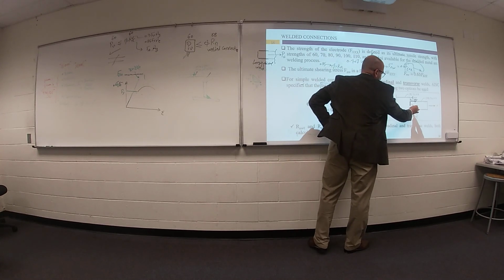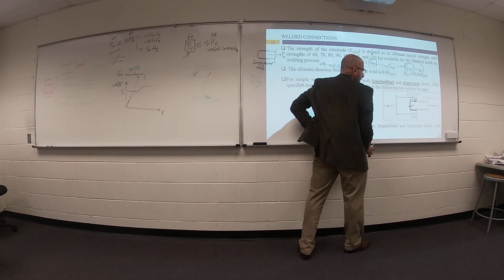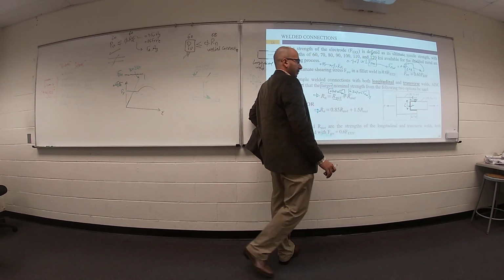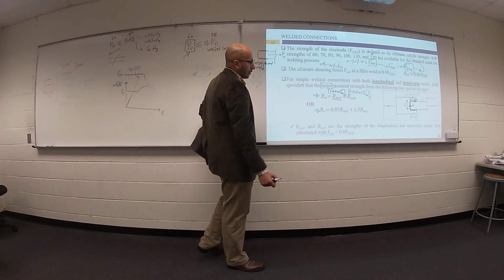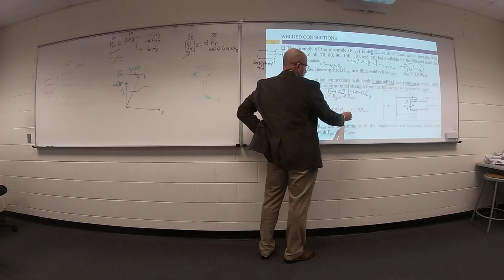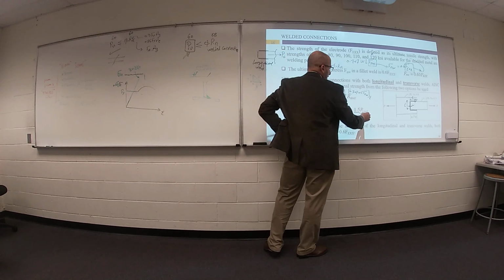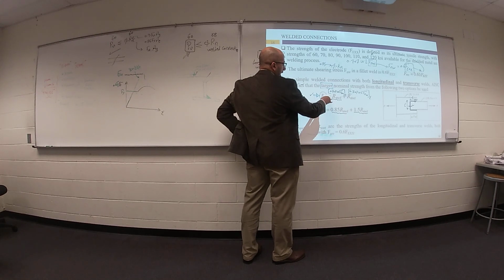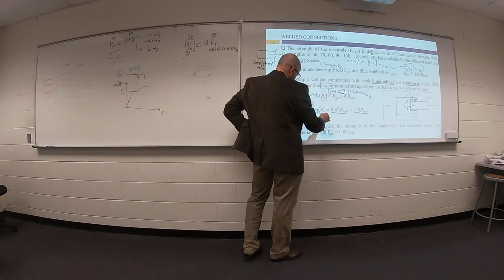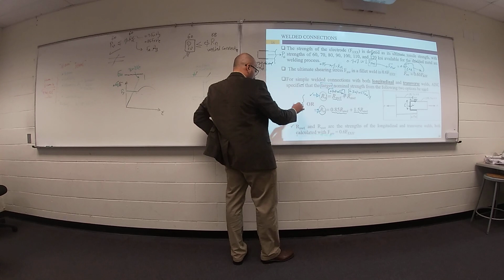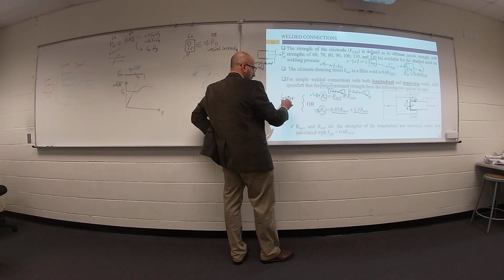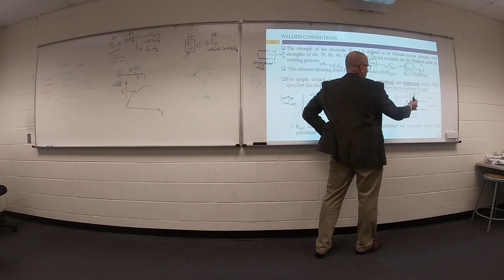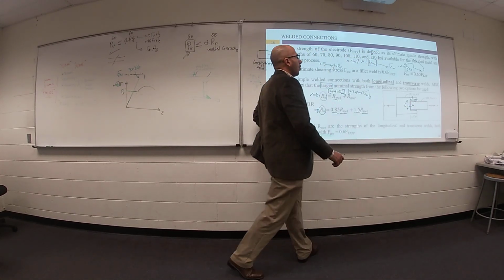The second term is for transverse. What is the W for this weld? What is the length for this weld? Or 0.85 for longitudinal plus 1.5 for transverse. Get a value for Rn in the first case, get another value for Rn in the second case, and use the larger value. This will happen only if you have in your connection both longitudinal and transverse weld.